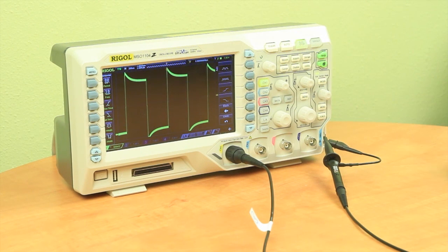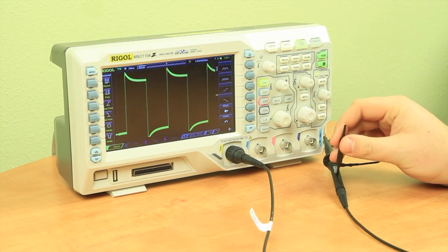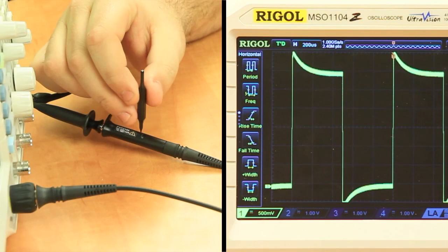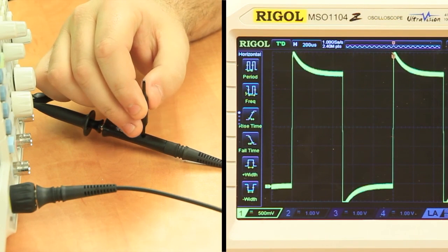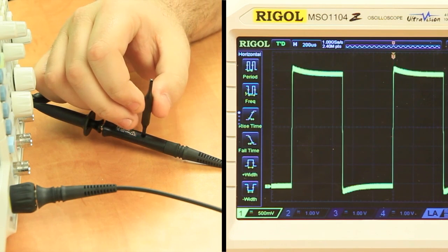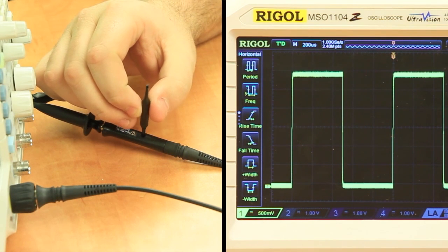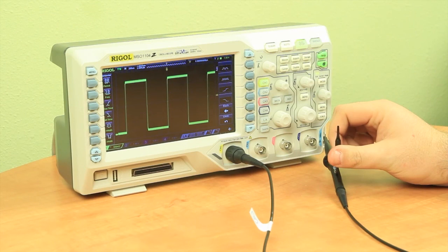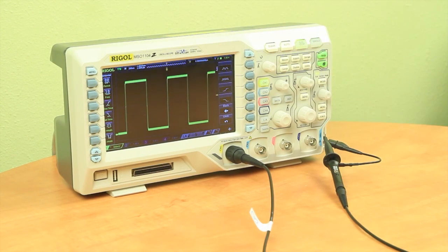And then with the screwdriver that was sent with the probe set, I'm going to change the capacitor in the passive probe to change the compensation. So right now the probe is overcompensated. I can undercompensate it along with properly compensate the probe. Once it's set here, you generally just need to leave it alone, but it's an important aspect for dialing in a new probe or a new instrument for a particular probe to get a properly read signal.